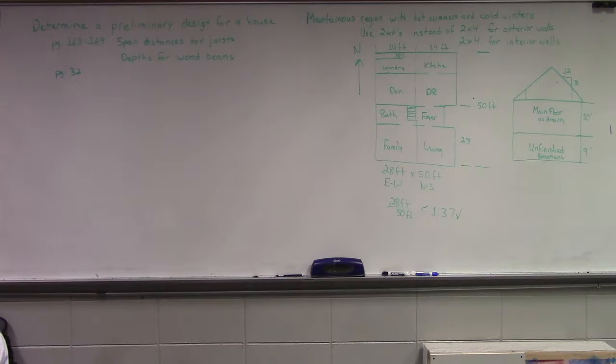Well, that gets back to what we talked about last semester. What did we talk about in the different framing styles, like balloon framing? Yeah, if it goes all the way through. So I guess you could, if what you want to do is get 19, or are you asking more for determining the shear wall? For the size. Do we have to move up a size to like 2x8 because we can't go 10 feet with a 2x6? Something like height restrictions on the sizes of your studs.